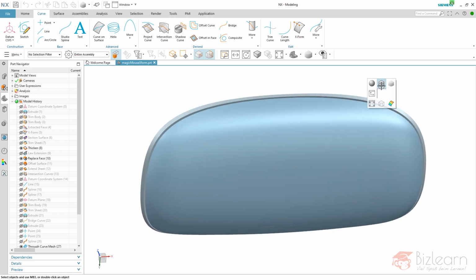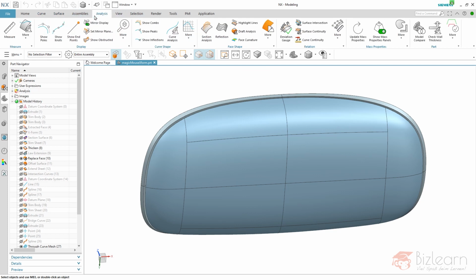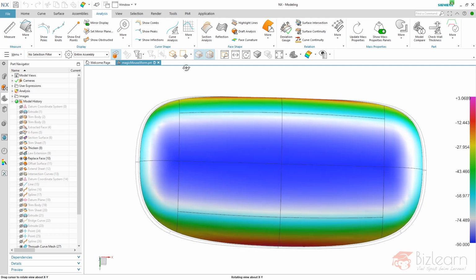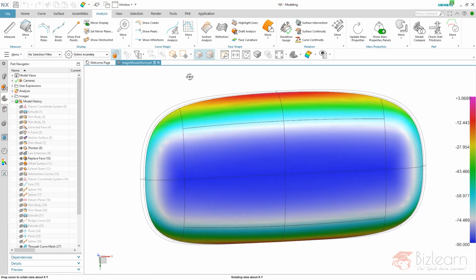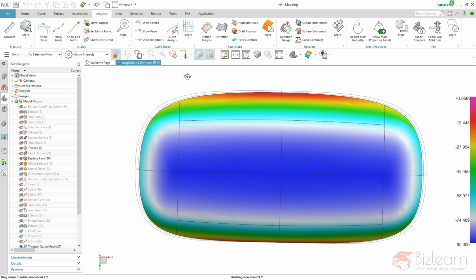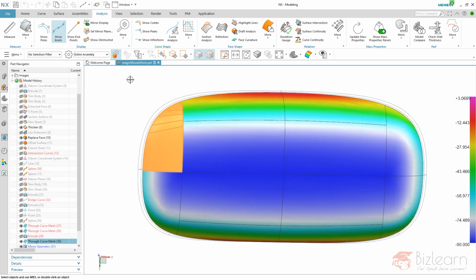But still, the big question here was, how can I check my curvature, bumpiness, smoothness? It was really hard to do by use of the reflection analysis, so I've decided to use slope analysis instead, which you might not have seen before. This gives me information of all the slopes within my surface and a possibility to control the smoothness, and well, I am satisfied with this, but it's still not 100% perfect.